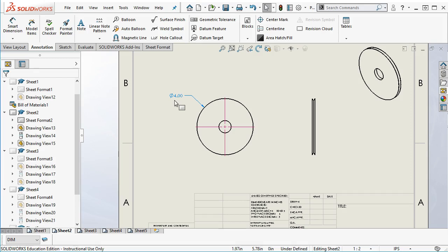Having super wide open tolerances only makes sense depending on your manufacturing processes and what you're using as a standard measuring instrument. If our standard measuring instrument is the tape measure, then yeah, I'm probably going to want to stay in 2 decimal places, but this isn't going to be very precise. We go to calipers, we're going to be a lot more precise. We go to micrometers, we're going to move up into that next level.